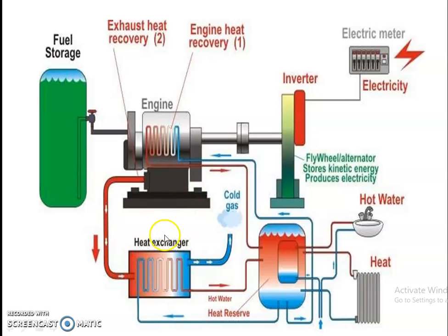Nowadays the government is fully focused on Bharat Stage 6, with a separate exhaust unit that combines the catalytic converter, EGR, and selective catalytic reduction, SCR. These three units combined as one unit dilute the emission to meet BS6. Also, the high amount of exhaust gas is used to rotate turbo machinery; the turbocharger is used for large plants.